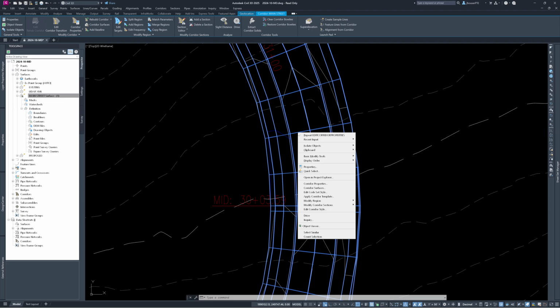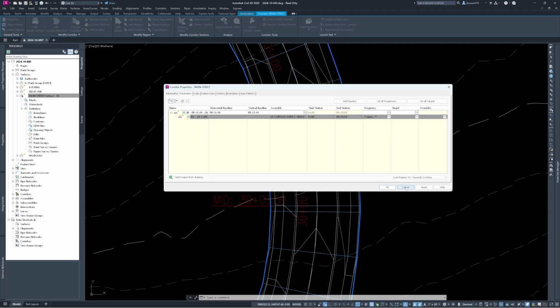Okay, Joel, yeah, that's something. The basic sidewalk does not have a slope associated with it in the subassembly. I'm not quite sure why. I typically don't use the basic sidewalk because of that. Let me change this back real quick and I'll go back up there. Okay, John Ilko said that the urban sidewalk option does have the slope. There are just so many different subassemblies that sometimes it's hard to figure out what exactly is the right one to look at.